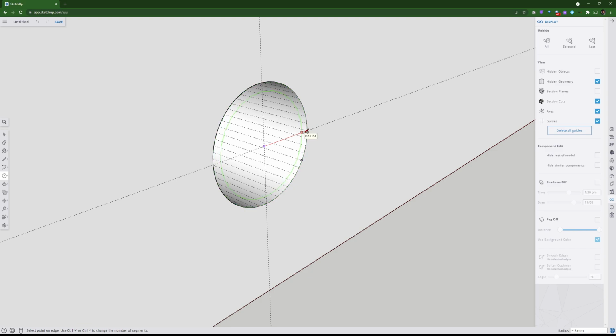When we do it in the workshop, we're going to do a 7mm hole here. That's so the axle will spin, will rotate, won't get jammed. But the drill bit is going to drill more closer to a 6mm hole in the center of your wheel, which will be perfect because that matches up with the dowel, the round timber that we're going to glue in.